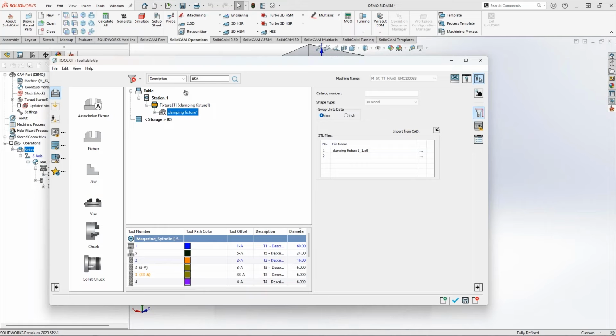With that, also here, you only see a table. You don't see any spindles. And on the right, it's pretty much the standard interface that we had in ToolKit. Now, what is the difference here related to a fixture? Now, for the first time, we can see and also manage part mounting. As both of these have the index A, it means they are associative. Associative means I'm connected to a 3D model. I can at any moment go back to this and reselect any other, change the coordinate system, add the coordinate system, remove the coordinate system, everything would be possible.